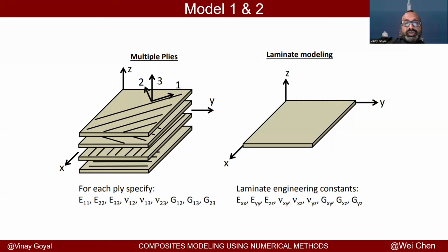Another approach is to calculate effective laminate engineering constants. And then I can use these engineering constants to determine the behavior in a homogeneous way. So we're not modeling every ply discretely, rather we're estimating the properties using a theory that's based on Chou's theory, whose advisor was Professor C.T. Sun. This approach allows you to estimate these properties. You can then provide those properties to this laminate.